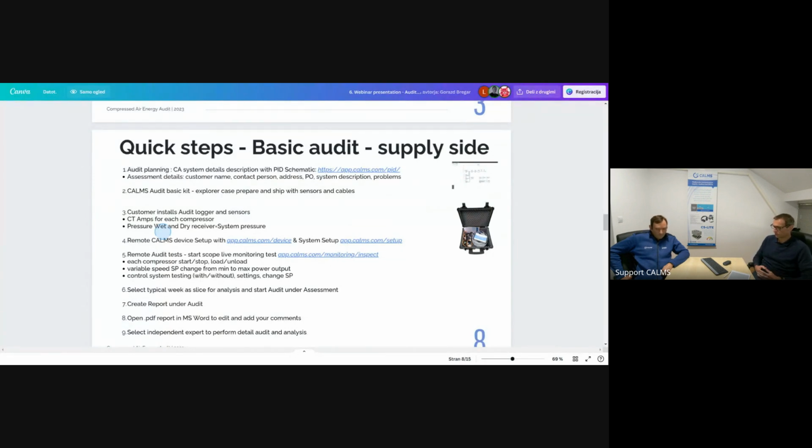Because of your problem, we would install, or you will install, 1 pressure transmitter at the end user, one in the compressor room before, and 1 after the dryer, because you said there might also be a pressure drop problem on the filters or the dryers. It is a possibility. We don't have any measurements in the plant, but we do know at some of our end users at what pressure they start to experience problems.